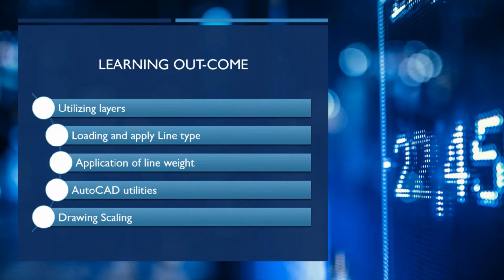You learned in architecture graphics that lines in technical drawing need to have a line width, a thickness. We have 0.2 pen, 0.1, 0.3, 0.4, and even 0.8. So for today, you're going to learn about those line widths and apply them in a technical drawing.